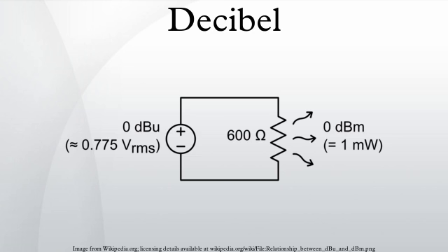Video and digital imaging. In connection with video and digital image sensors, decibels generally represent ratios of video voltages or digitized light levels, using 20 log of the ratio, even when the represented optical power is directly proportional to the voltage or level, not to its square, as in a CCD imager where response voltage is linear in intensity. Thus, a camera signal-to-noise ratio or dynamic range of 40 decibels represents a power ratio of 100 to 1 between signal power and noise power, not 10,000.